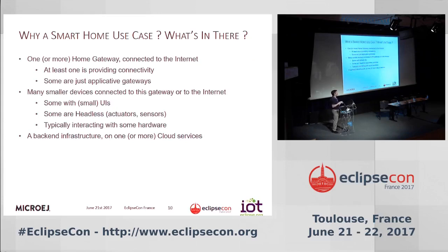And typically in a smart home deployment, in smart home scenarios, there are also many devices in the house that are directly connected to the gateways or directly connected to the internet, and those devices fit into the constrained devices area, because there are many of them, so the cost is important. You cannot afford the same price as a gateway for a switch, or for a bulb, or for a temperature sensor, of course. So you have to build these devices with cheap microcontrollers, cheap systems, right? You have to issue them in volumes. You can tell that for one gateway there might be 10 or 20 devices connected to it, so the price,